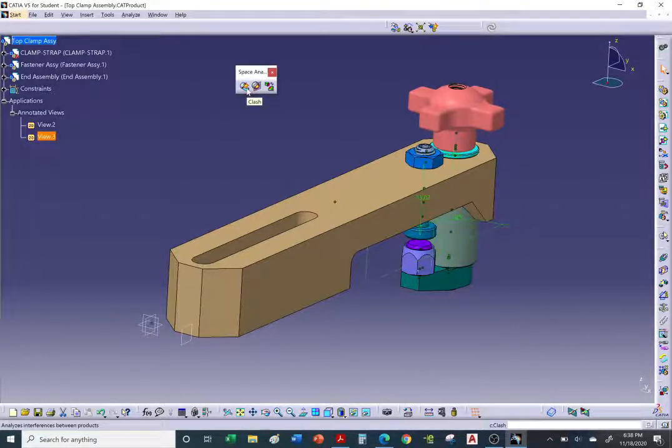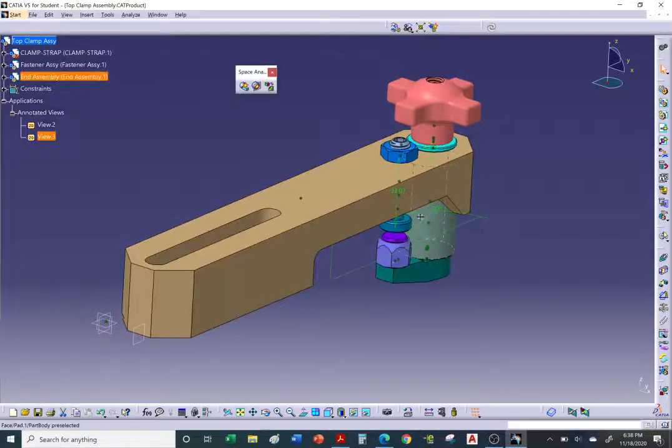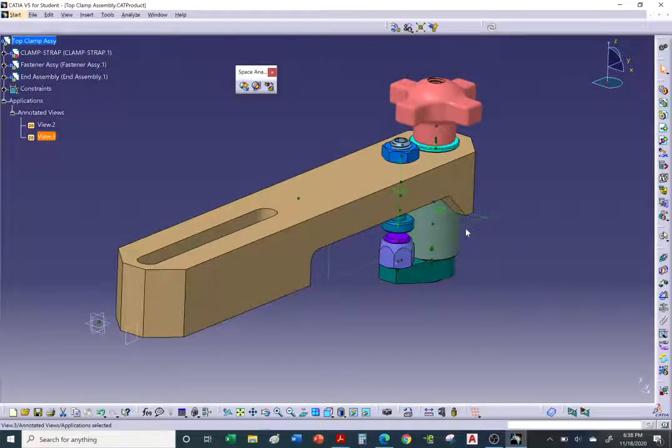So we're going to do a clash. We're going to check to see if there's any things hitting each other or parts buried in each other. Again, as I mentioned a few slides ago, we always ran a clash analysis on the vehicle we were working on to make sure there were no components hitting each other, whether it was interior hitting structural components or electrical running through structural walls, for example. So we always had to do a clash analysis, especially when you have thousands of components.